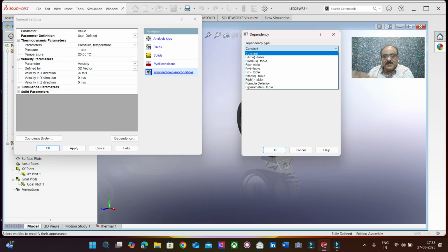Okay, so now we have understood what the temperature is going to be, and that temperature is what we are going to give for the LED bulb here. We don't have to perform an optical simulation to find that out. Instead, we are defining that this particular projector lamp is going to be used for this application, and the illumination capability is going to be this, and when the illumination capability is this, the temperature is going to be this. So now we have arrived at that temperature, and we are giving that as the input.